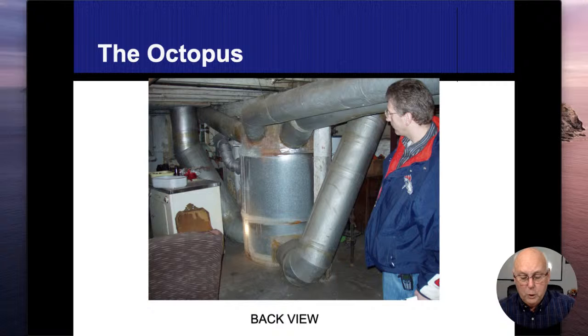So the returns. This is a return. Back here is a return. These things are supposed to be 3 times as big as whatever the supplies are. So these are supplies. Typically these are going to be 8-inch ducts that go to the different rooms, and these would be 2-foot returns that come back. Again, no filter, no fan, or nothing else.